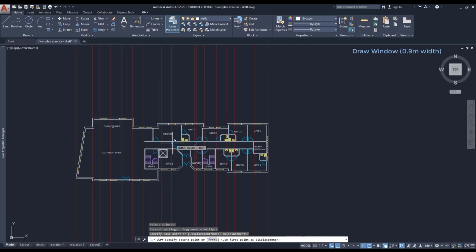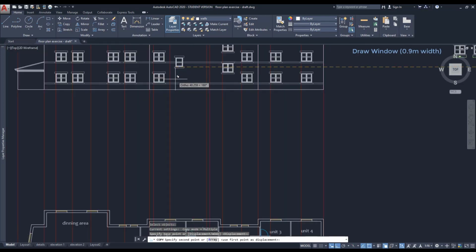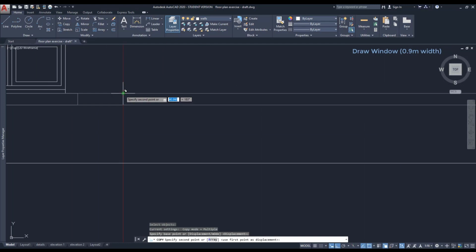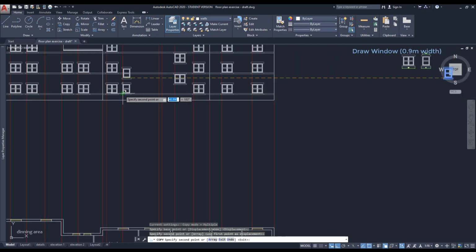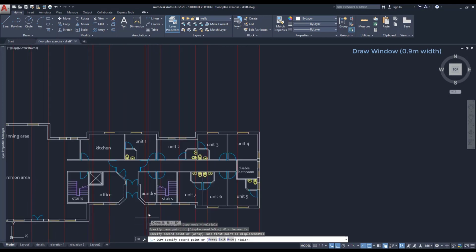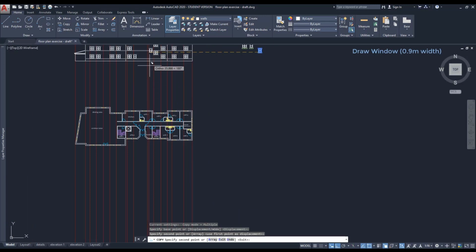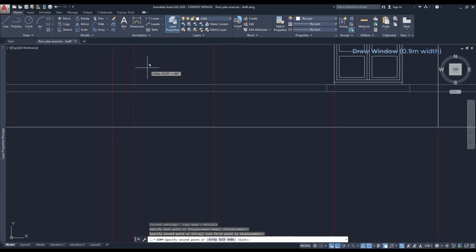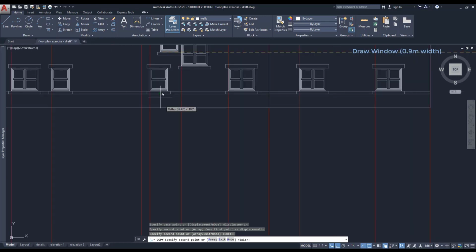Following the guidelines, slowly I can click it in the right intersection. Now I just need to do the same for the window at this side. Slowly. Now I'm going to zoom and click there. If you noticed, I was with the ortho mode turned on, and even it looked a bit confusing. It's okay since you click on the correct object snap point.